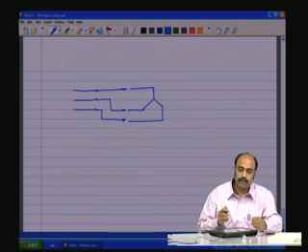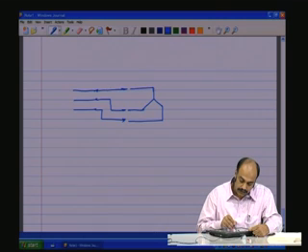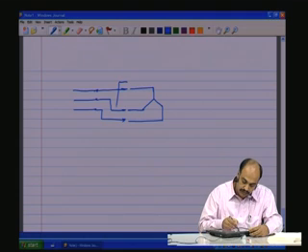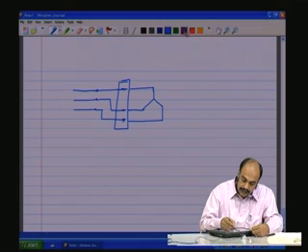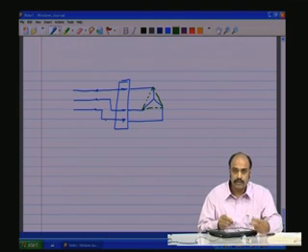When the motor is getting started up, we apply the motor windings in a star fashion, which means the phase voltages are reduced by √3 times, and then we have some kind of a switch mechanism such that as the motor has picked up speed, we put this in a delta fashion such that the winding voltages see the line to line voltages, which is a higher voltage.